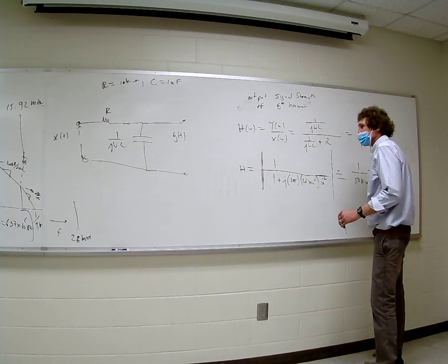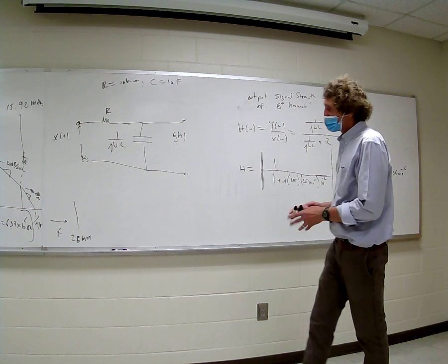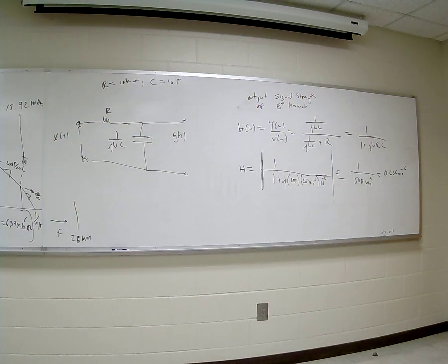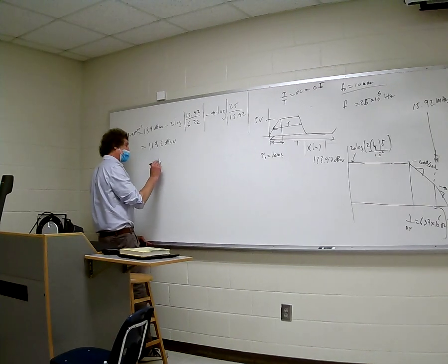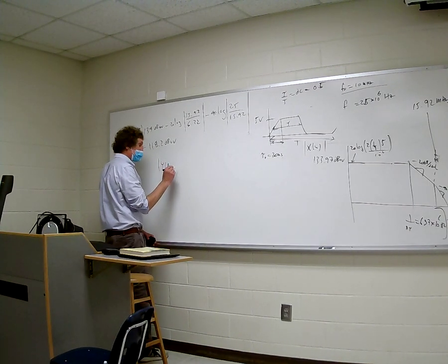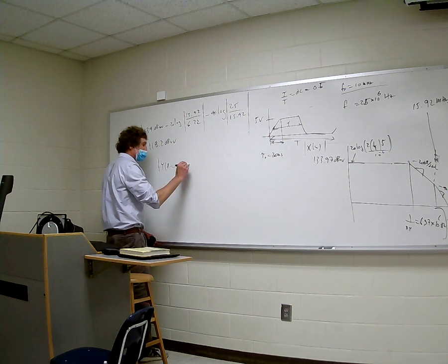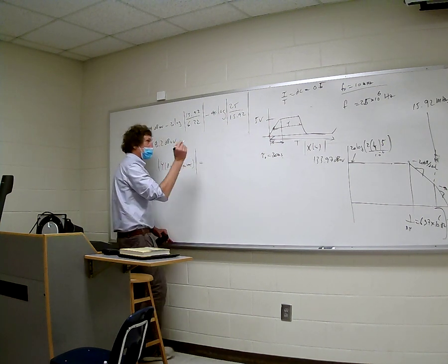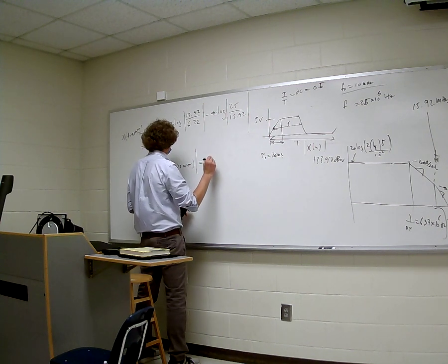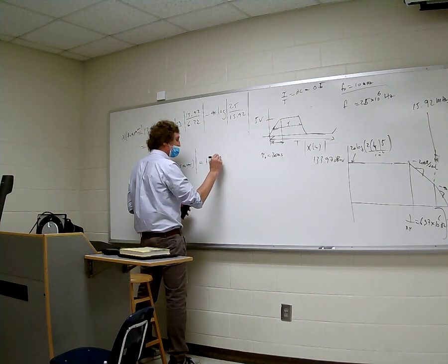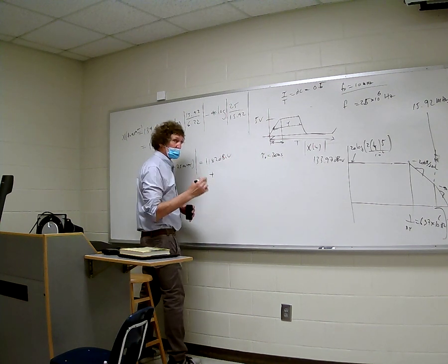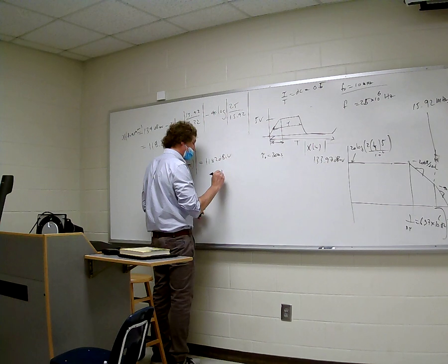So now what you do to get the output right here, I take this output value. What I want is the magnitude of the output at f equals 25 megahertz for the filter I've gotten, which is this value, 118.2 dB microvolts. Then it's technically a plus 20 times the log.